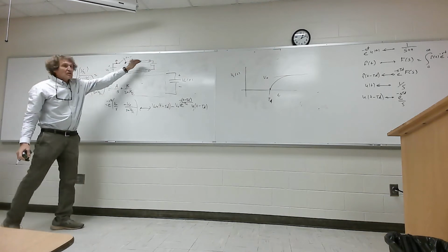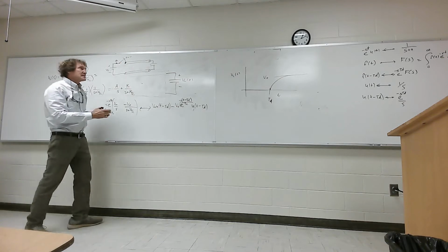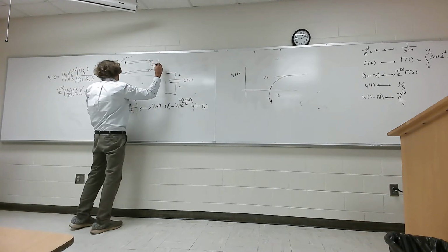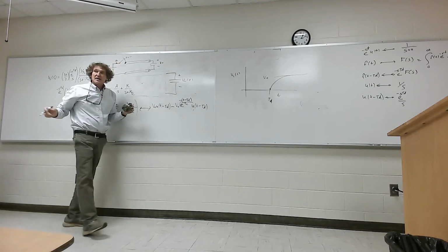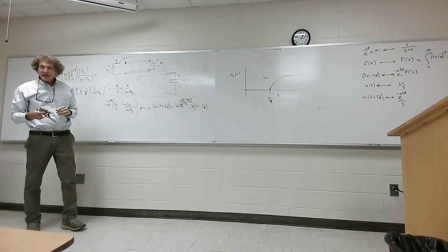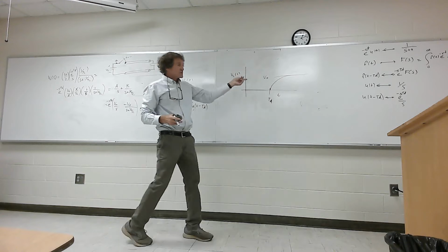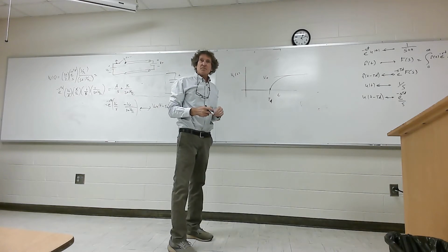Well, current's going to flow, right? It's going to keep flowing until it develops a voltage that's equal to and opposite V0, and then it stops. So that is the asymptotic value it approaches when you have a capacitor termination.